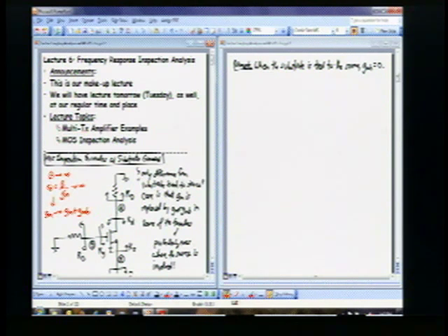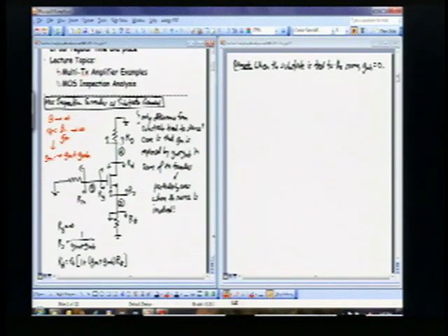This has to do with the body of the MOS device. A bipolar device is a 3-terminal device, and an MOS device is a 4-terminal device. The 4th terminal is the body, so we have to account for its gm in certain cases. When do we have to account for gmb? When there's a body-source bias. Exactly. In cases where we tie the source to the body, you don't have to worry about gmb.